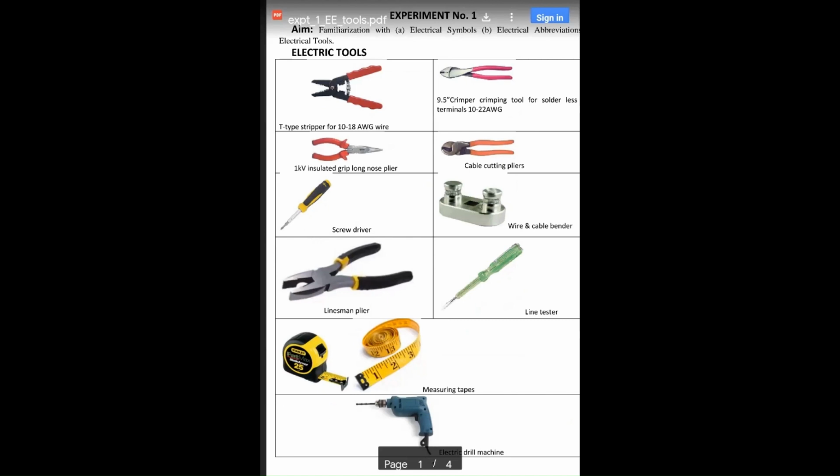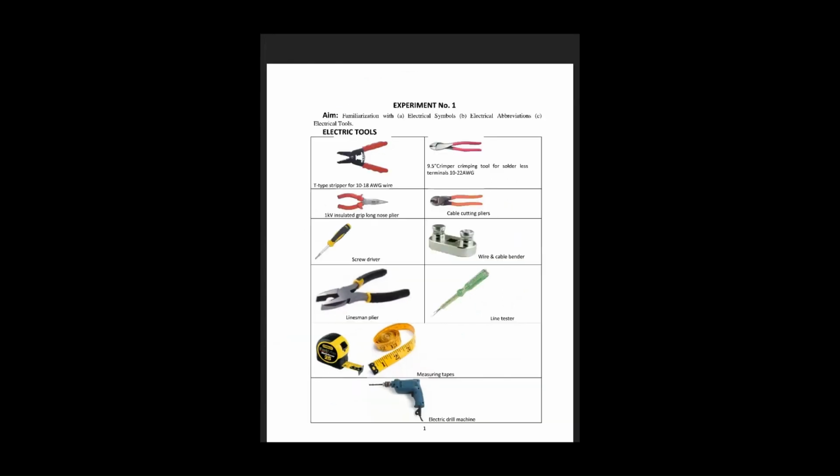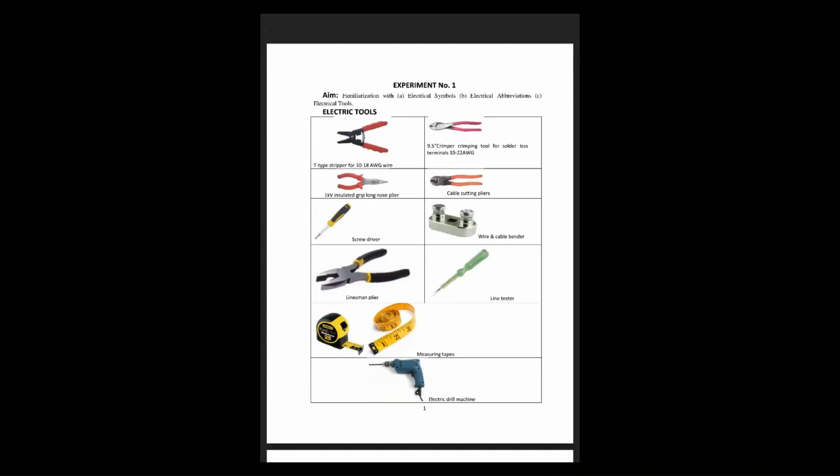So cables are given some numbering, and based on that number we can purchase and use the wires. As the number increases, the width of the cables decreases. So a wire gauge is a circular metallic portion with circles in it. The bigger the circle, the thicker the wire, and some numbers are assigned to it.